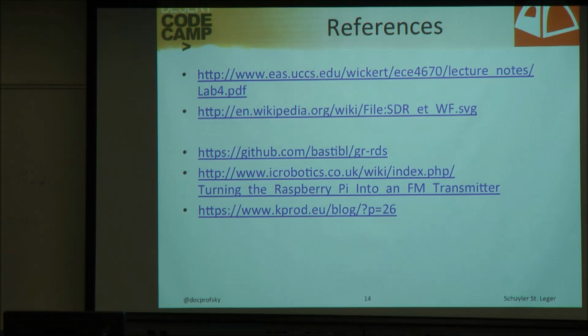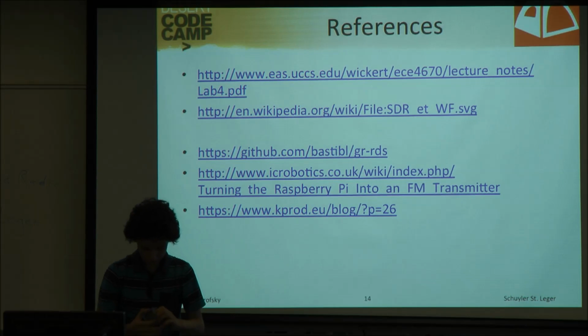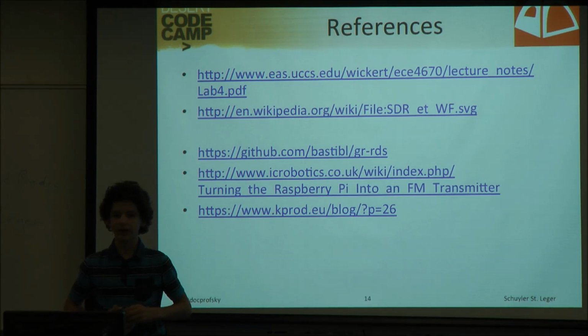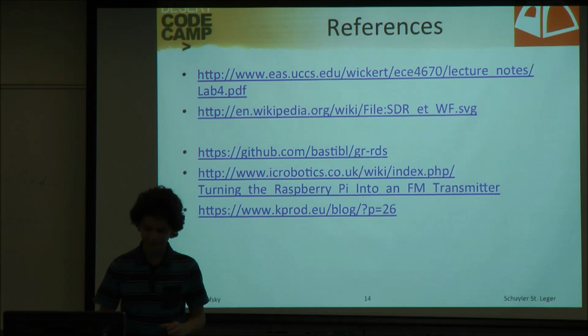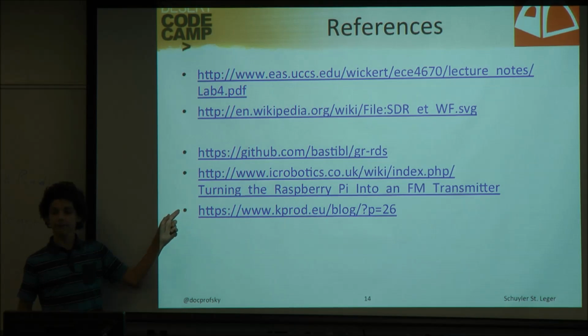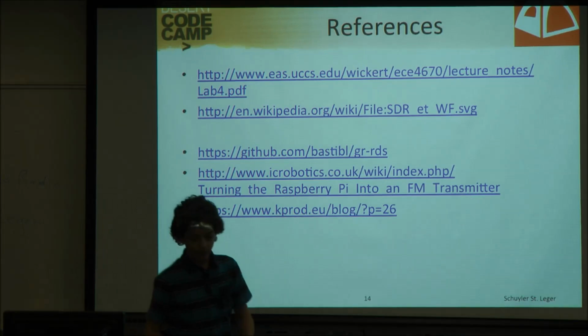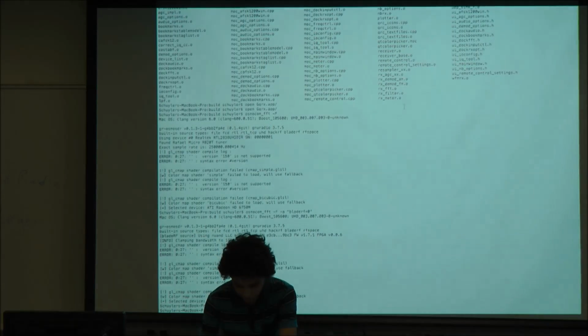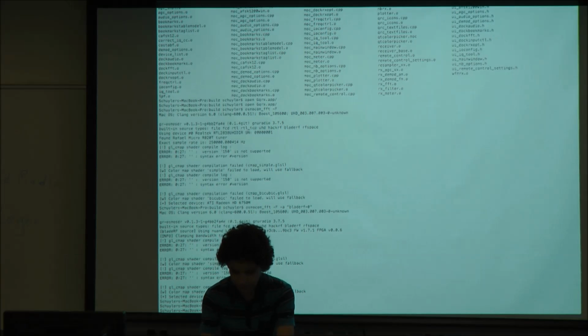So the Raspberry Pi, have any of you heard of this? The Pi has an FM transmitter. On GPIO line 4, you can transmit RF data if you just connect an antenna to there. It has to do with when you read memory, it leaks RF, so if you read it correctly, you can do stuff. And then this is about using the Pi as a modem too. One other thing I'd like to add is here's a good diagram of the quadrature signaling. What is it? Quadrature.